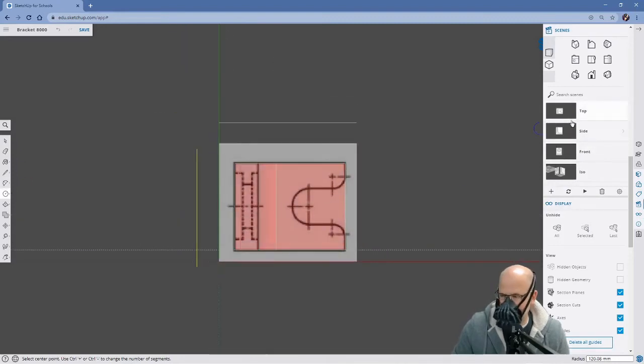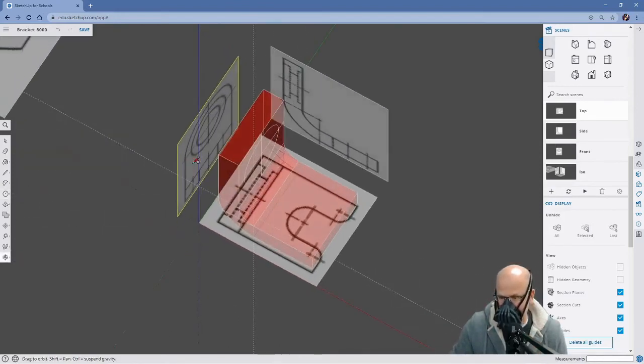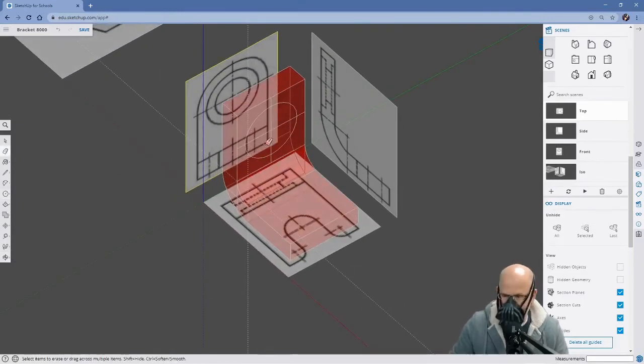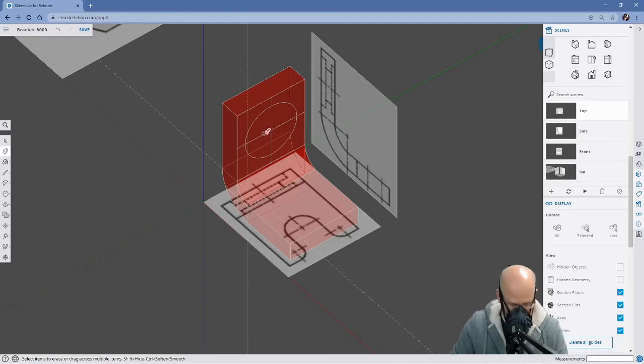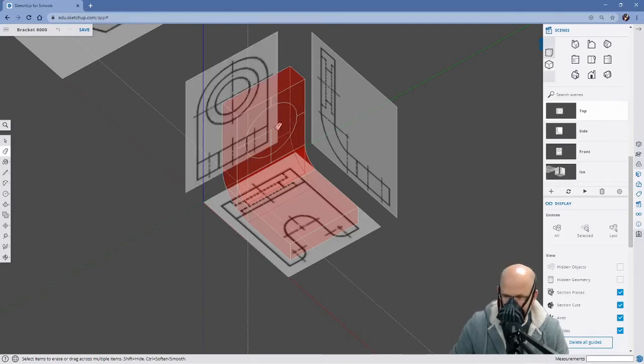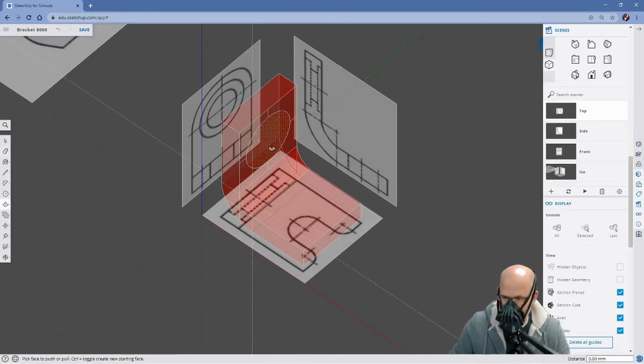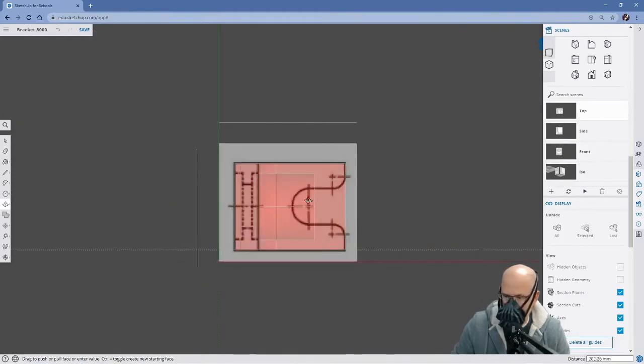All right, now that I'm in X-ray mode still, notice that if I go to the top view, I can actually see how far that circle that I created needs to be pushed in. Okay, so I'm going to go back slightly. I think I can remove these lines real quick. Oops, Control Z, that's okay. All right. I'm going to push pull. And while I'm push pulling, I will click top so I can see. I'm going to go to right there. All right.